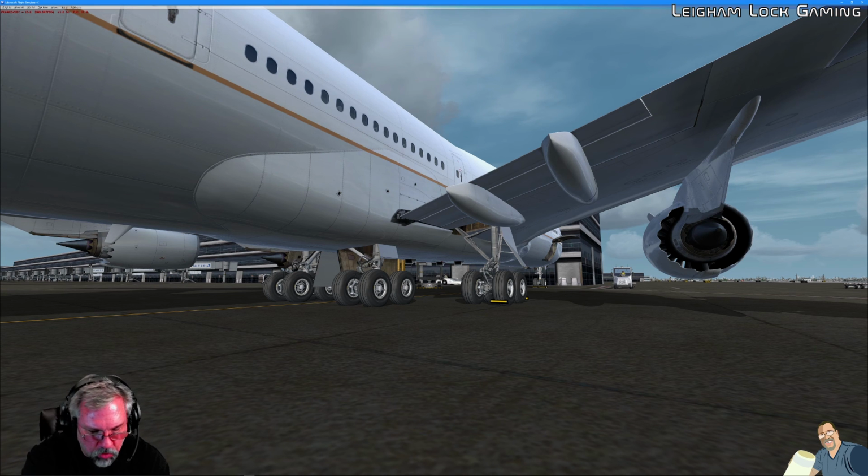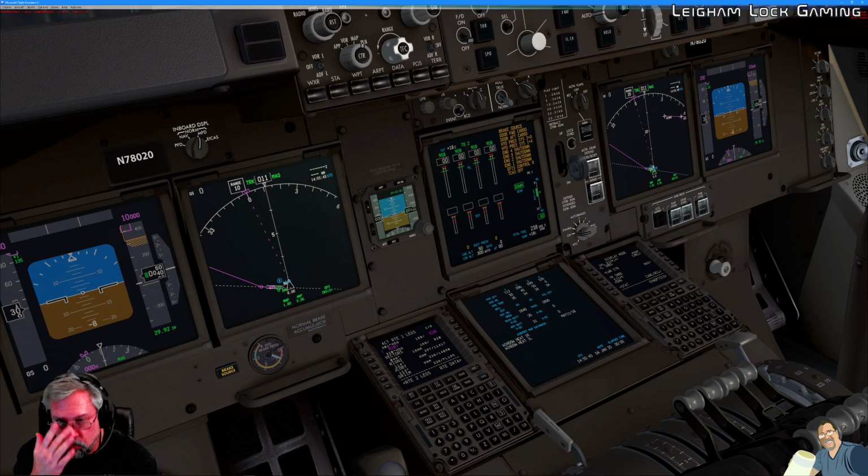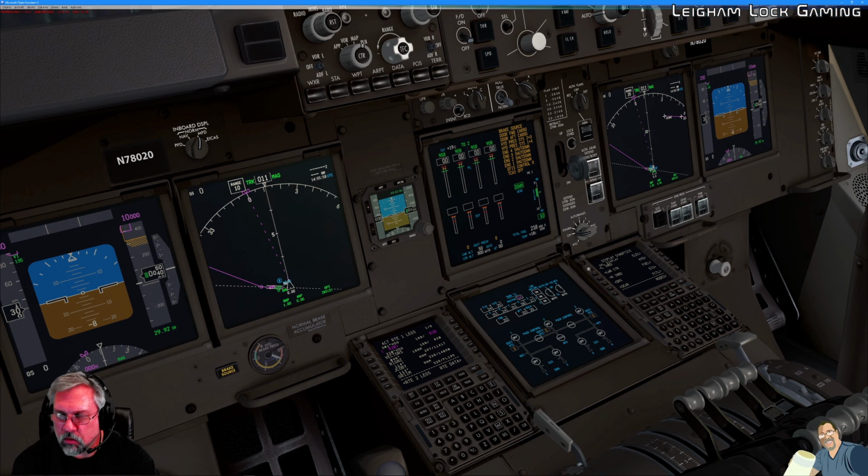At this point, we are almost ready to request boarding of passengers. One thing that is a good thing to check is our environmentals. If we go to our synoptics page and look at ECS, our environmental control system, we can see that the temperature on board the aircraft is a little warm in the back of the cabin, but pretty close to what the master setting is.